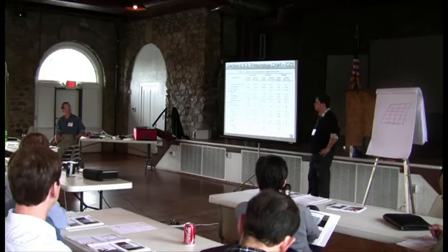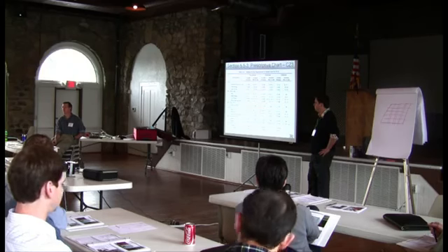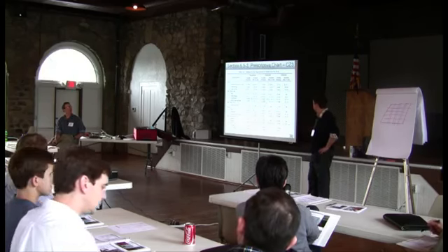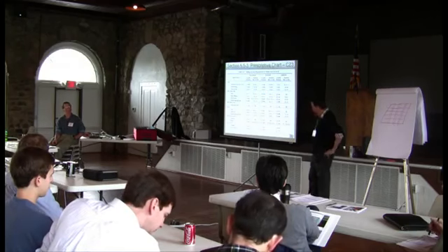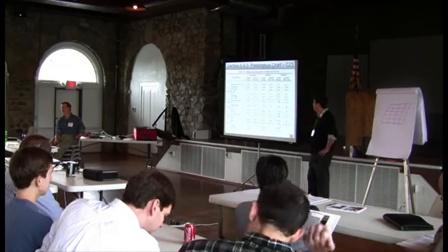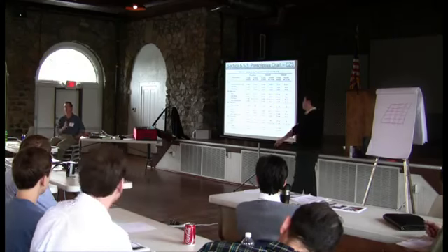So we good? The main thing is everybody understand what's a mass wall, right? Concrete or block or a solid brick wall. What's a metal building? We know what that is. Steel framing, we have to put foam board, and wood framing we don't. So this is again the prescriptive code. You can do trade-offs, but this is knowing the prescriptive code.